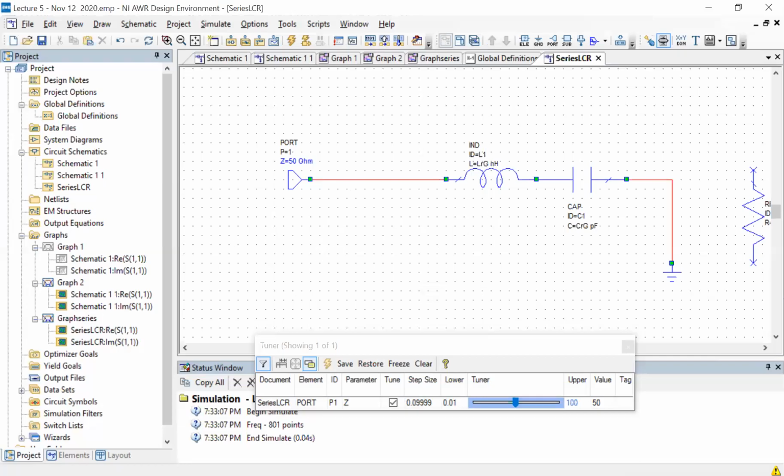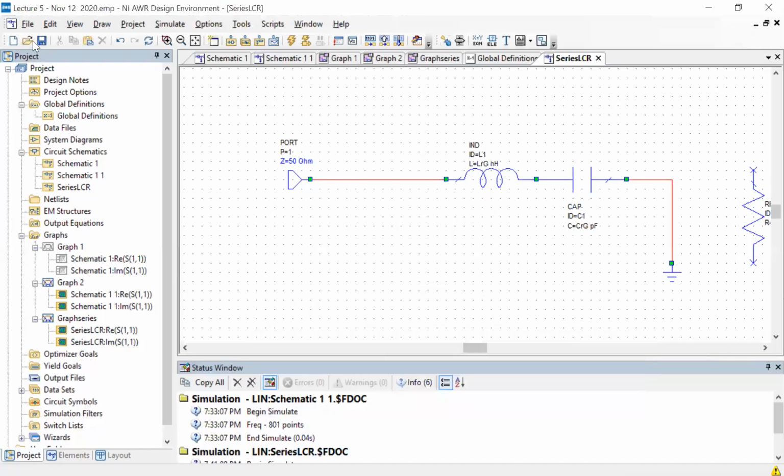All right, any questions? So in the previous situation, we could improve the quality factor by adding a capacitor in series, by changing the voltage difference. Yes. So here, since it's not voltage anymore, it's the current which is traveling through the resistance which matters. So would the equivalent of that be something like adding an inductor in parallel or something like that? Yes, that is a very good question.